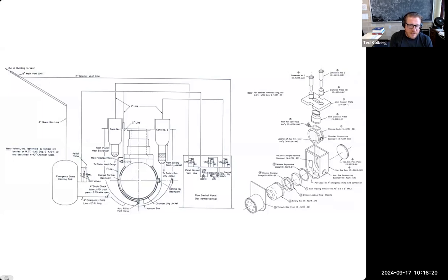And you can get an idea of this complexity from looking at some of these mechanical drawings. These are for, I think, the 30-centimeter bubble chamber at CERN, but many of them would look similar. So you need a whole array of services coming in and out. You need some to be connected to some external services to allow the expansion of the gas. You need these condensers to keep things in the liquid form. You need to have portholes in order to enable the photography, and these portholes have to be able to withstand tremendous pressure. So you're using very thick glass that introduces complications about optical distortion of the photographs.